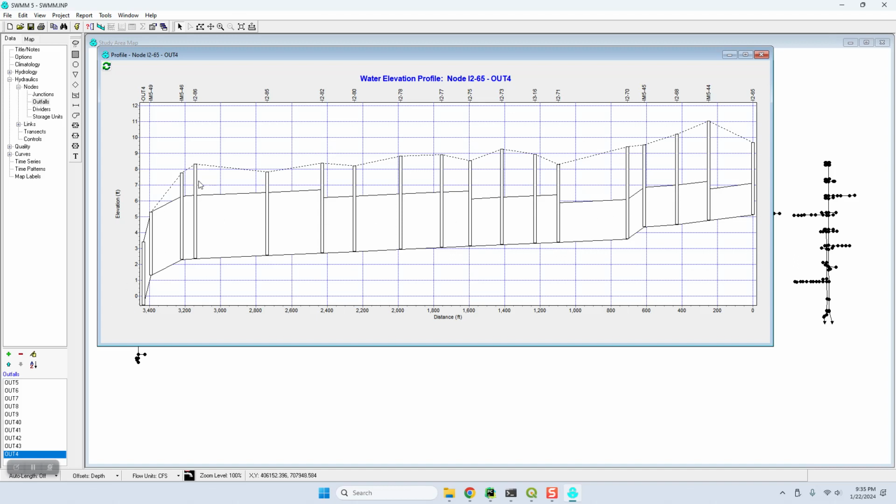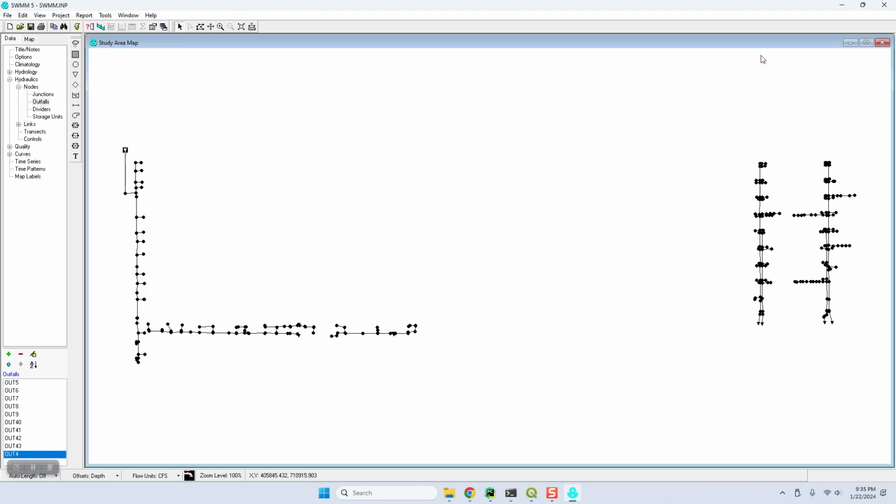conduit, or excuse me, the line. And this one is actually out in the river channel, so it might have a tidal influence on this one. I don't have a tidal influence set up on this one, but it's definitely something that you could do in a more advanced lesson. So we're going to close this, and I do indeed check all of those lines before I run the model just to make sure that they all look correct.